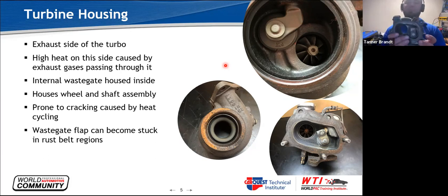And you're not going to have any boost building. The other thing that happens in Rust Belt regions, Lucas, you guys being in the mountains, this will happen. If something sits, guys that tow campers, they buy a truck and it's seasonal, they drive in the summer, in the winter they put it up, this wastegate will stick, it'll rot.